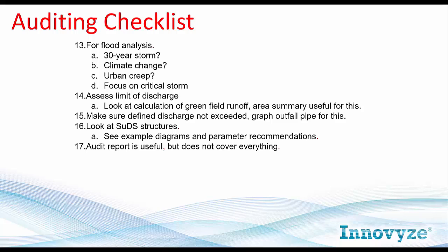A couple of things I haven't mentioned that should be on this list is, number one, make sure you check for instabilities. Despite our best efforts, some models do become unstable, so use the graphs for oscillations in the flow. If you find any, get in touch with the support team and we'll help you work through them.